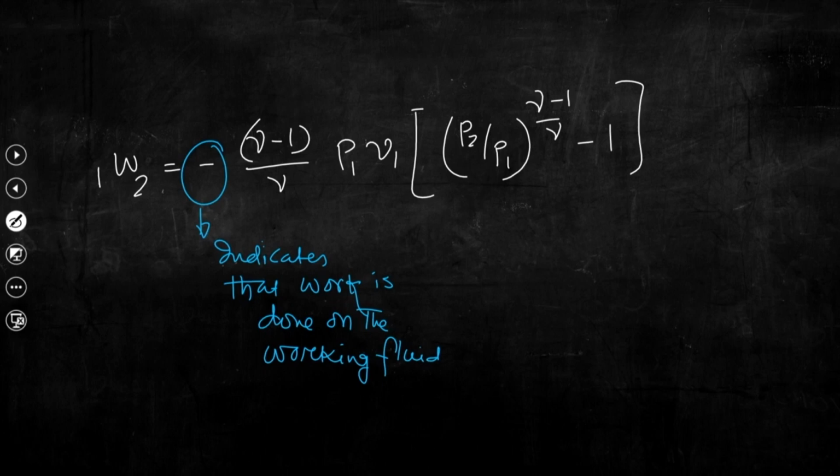If we increase this pressure ratio, then compressor work, that is the negative work because this is the work consumed, will be more. So, these two are very contradicting. That is why we had to establish the optimum pressure ratio for which the cycle efficiency will be maximum. So, this is the expression of the work ratio for reversible adiabatic compression.